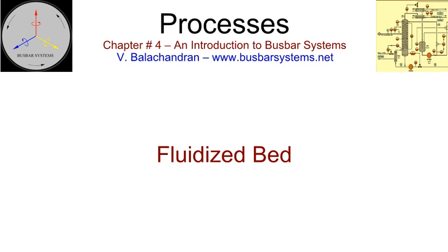After the bus bars are removed from the fluidized bed, they are transferred to an oven for post-curing. The temperature and duration are recommended by the epoxy powder manufacturer.